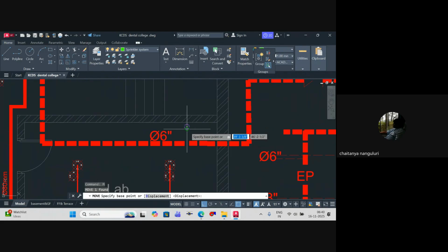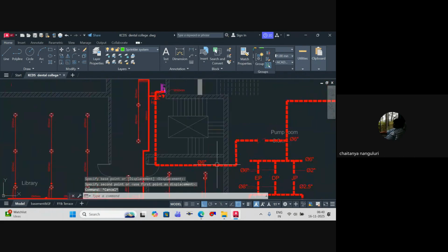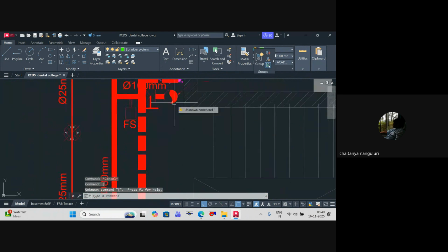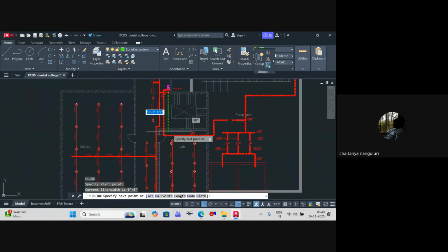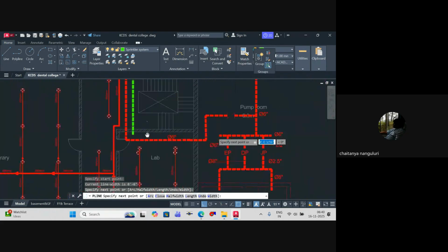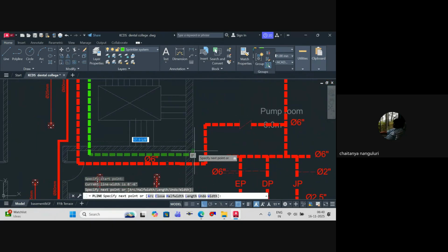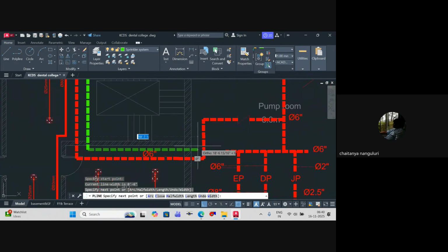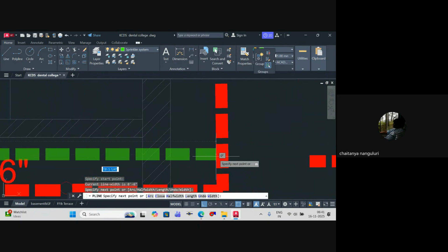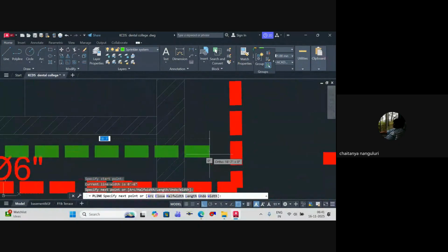So what I'm going to do is I'll take this line parallel to this and then one more line I'll write, which will be connected from your discharge manifold. Obviously, the NRV was over here, so I have to take it in this fashion. In this case, I can place the NRV internal to the building once it reaches inside, or in the pump room. Any one of the things is fine for us. Before the NRV, we have to connect it.